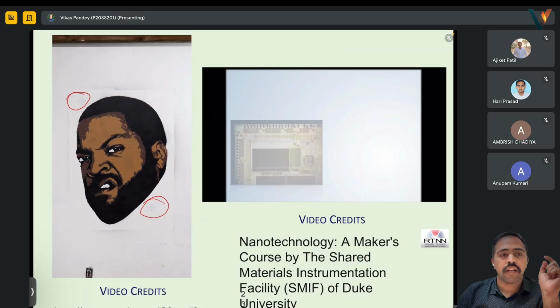So if you have to deposit something over it, it will go on like that, and there will be a break. Are you understanding? Fine. Suppose we use a chemical remover, it will actually remove some part of this, because it is different. If we do our deposition, we will get better results. That's why this is very technical, and negative is preferred for smaller dimensions as well, where we cannot etch, like gold and platinum, which may not etch easily, so we use lift-off. PR is common.